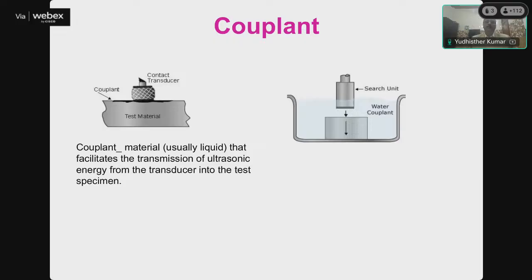This is for immersion testing. Here a container is filled with water. This is the test material. This is the transducer immersed in water, and here the water works as a couplant.